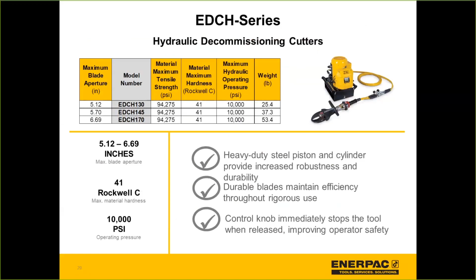We've got 3 different sizes of tools that can power through materials that are up to over 6.5 inches in diameter. And so when you look at the picture on the right here, you'll see the tool is attached to a hydraulic pump. And you might notice that the picture looks a little bit different than some of the other hydraulic solutions that we offer. And the difference is this: there's no electric cable there, okay? So what we have is a twin hydraulic hose attaching the tool to the pump.